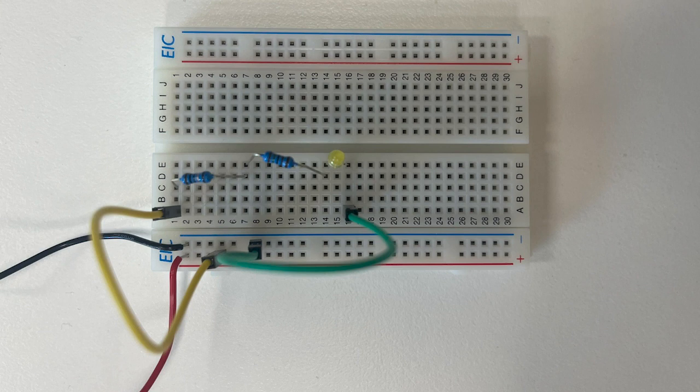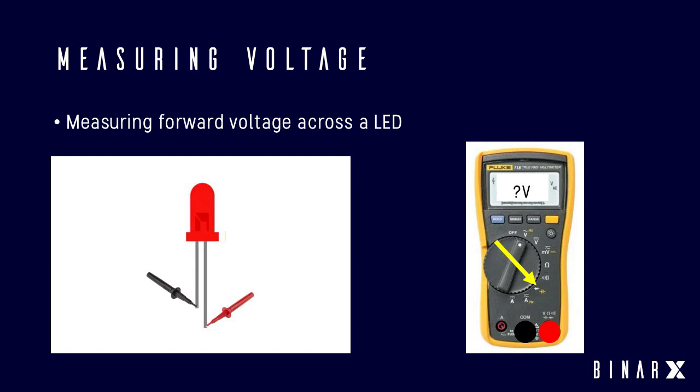The thing some of you might have noticed is that the LED only turns on when you measure it in one direction. The reason is that an LED is a polarized component, which means it only works one way. That's what the line on the diode symbol means. That line indicates that current will not flow through in that direction.